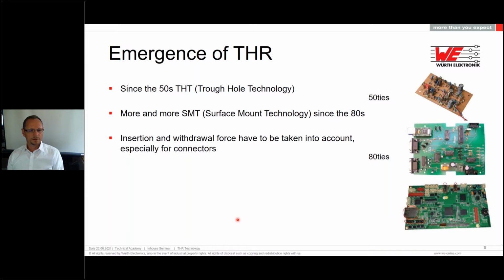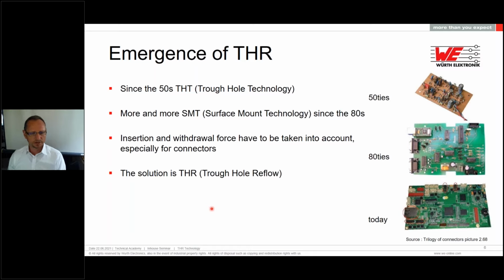What was obvious pretty soon there, if we look here to some kind of connectors, is that if you apply force to a connector, it's better if it's a through-hole component, so it can absorb much more force. With the SMT pads, they can be taken off from the PCB. So the solution in many cases could be THR, which combines the advantages of both technologies.